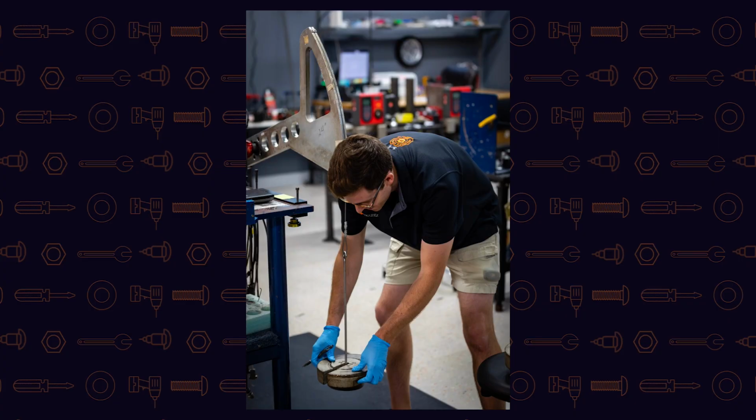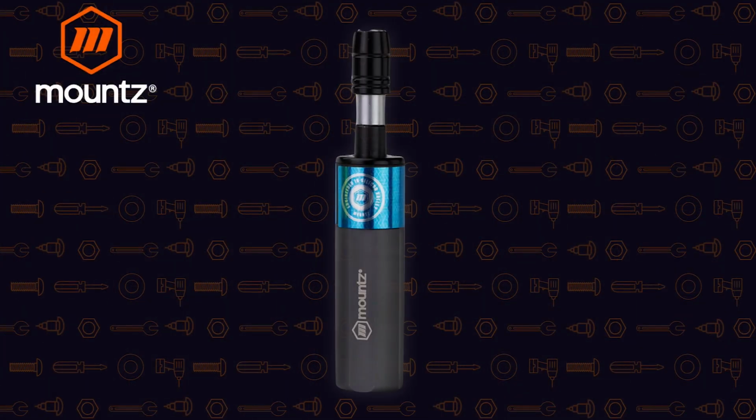So that's how the torque analyzer is actually reading the torque that's being generated by the tool that we're testing. We are adding torsion to the stock, which is changing the electrical signal from the strain gauge, which was calibrated through the use of the segment arms and dead weights.